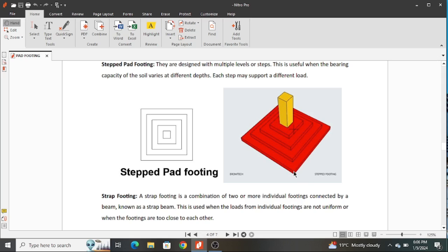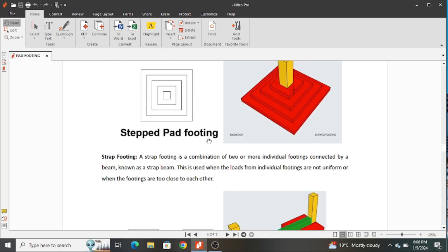And sometimes you can even concrete this entire section so that you can have a sloped footing. This takes care of concentrated shear at just this column junction. And there are two types of shear it takes care of. One is shear at the face of the column and shear at a distance d from the face of the column, which are governed very well by the codes.